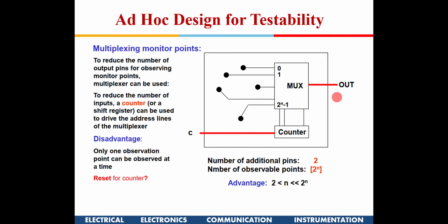Now the advantage here is that only a single pin is being consumed. That pin is just to start the counter, and probably one more may be required to stop it, or you can design it with the same signal. Once the signal goes high, the counter starts from 0 0, and when it comes back around, it will reset to 0.